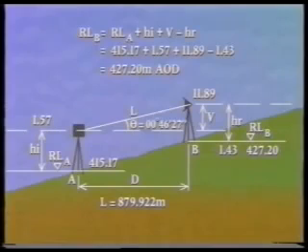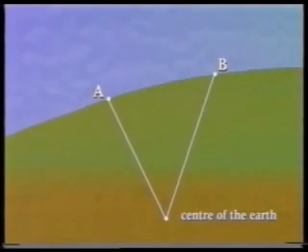For most everyday surveying work, horizontal distances and reduced levels can be obtained like this with only the atmospheric, prism, and slope corrections being considered. However, if the distances are to be used in conjunction with the Ordnance Survey National Grid Coordinate System, then they must be reduced to their equivalent lengths at mean sea level, MSL.